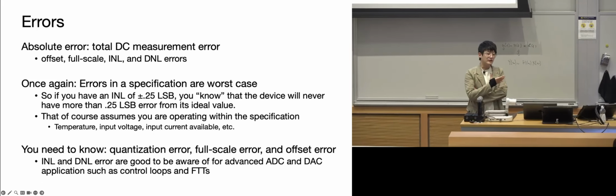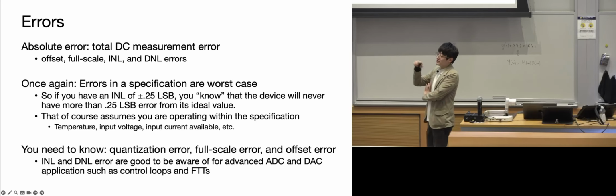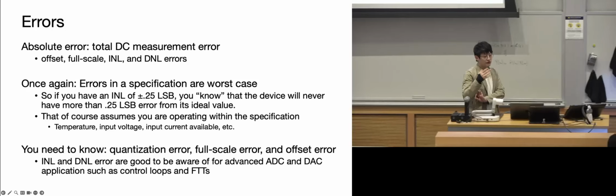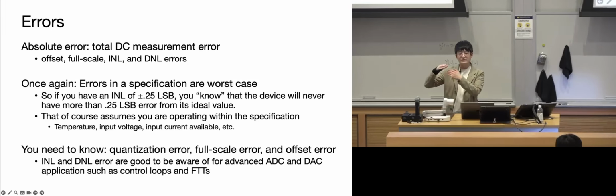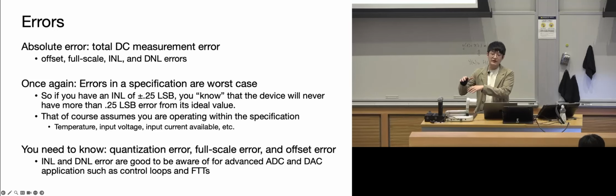Make sure that whatever use case you have is within the measurement range or the intended accuracy of that hardware. Typically on a DAC or ADC, you will see a plus or minus sign somewhere, either in dB or in voltage proportional to the reference. That's essentially the accuracy of that piece of hardware.